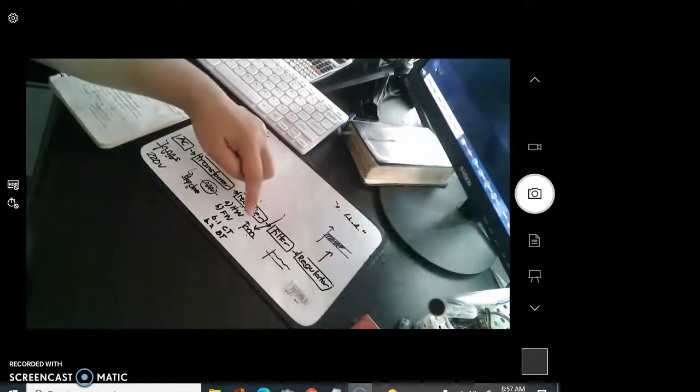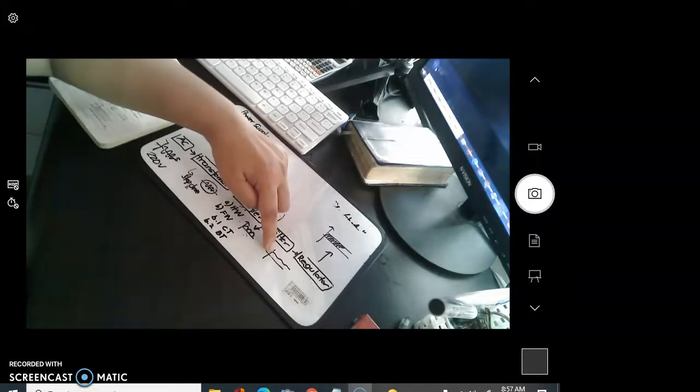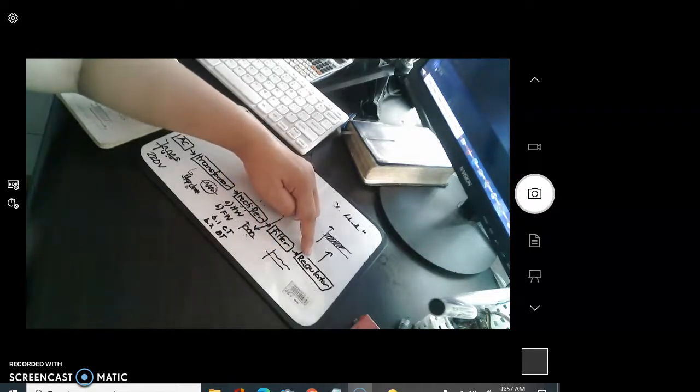Okay? So after this signal passes through a filter, the filter with a capacitor smoothens the signal. But then again, this is not the target voltage, but rather a flat voltage. So it has to pass another circuit, and that is a regulator. The responsible component in regulating the voltage to a smooth, flat signal is the regulator circuit. The main component for a regulator circuit is the Zener diode.